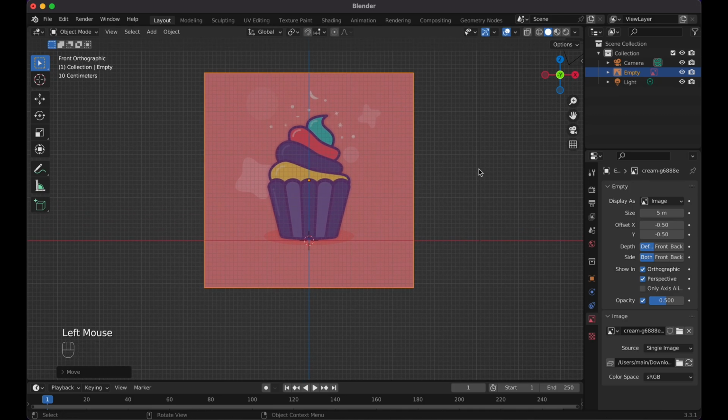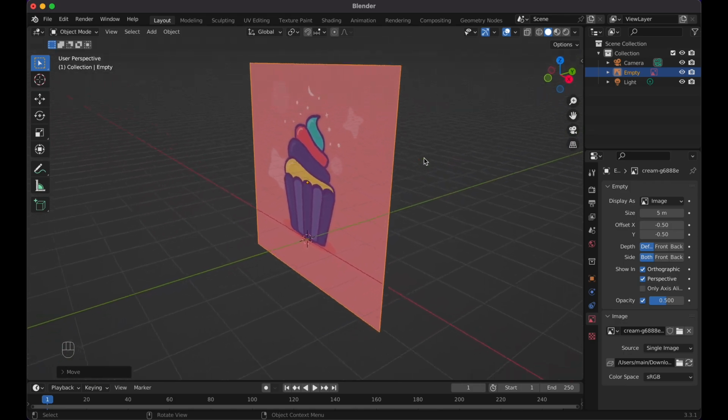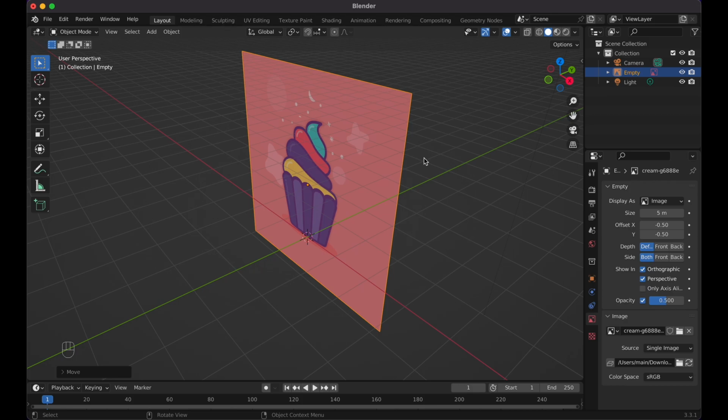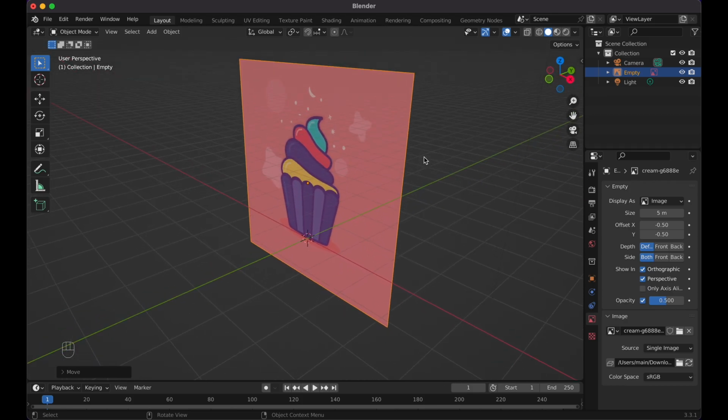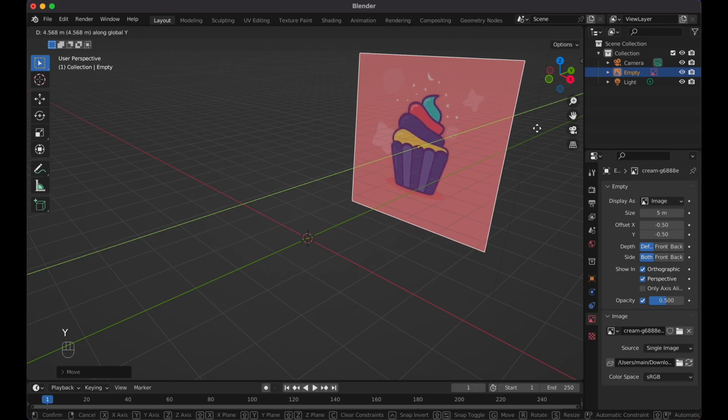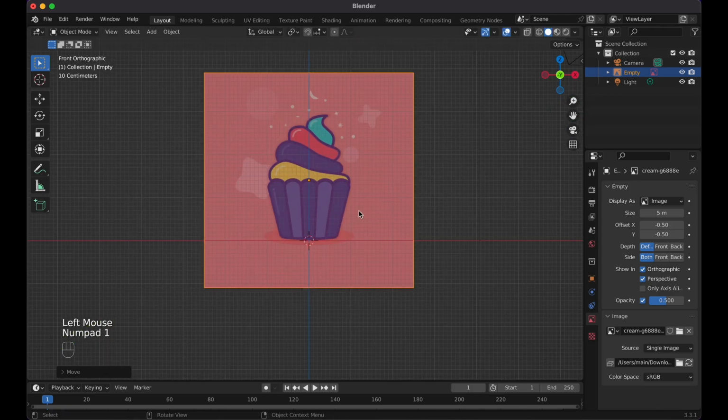Now, since this is only the front view, we don't have side views, but for the sake of this one, we really don't need it. But it is better if you did happen to have top view, side view, any type of view to make it easier to make the 3D, then that definitely helps. But let's go ahead and do G to move, Y, and we'll move it like 3-4 squares back. And then we press 1, now it looks normal.